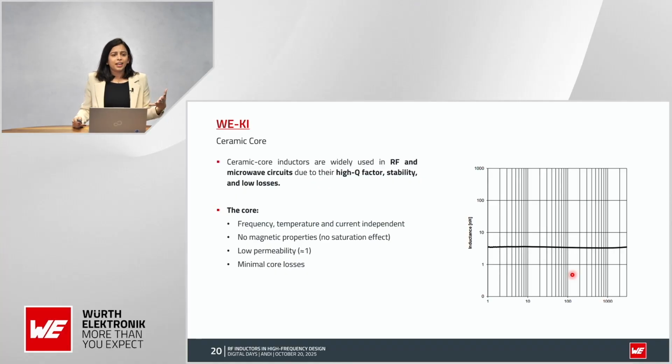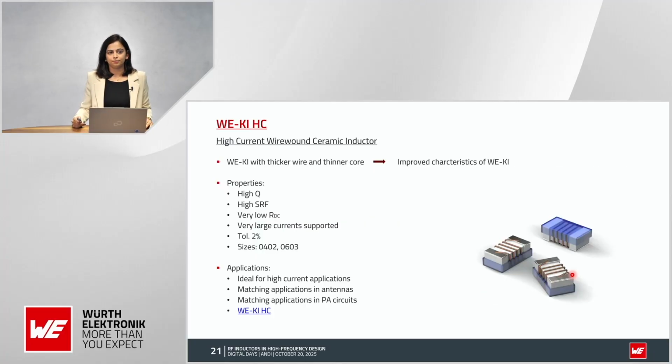Now, the ceramic core inductors are widely used in RF and microwave circuits due to their high quality factor, stability, and low losses. The ceramic core is frequency, temperature, and current independent. Because it's a ceramic core, there are no magnetic properties, no saturation effect occurs, very low permeability, and minimal core losses, as we can see in this.